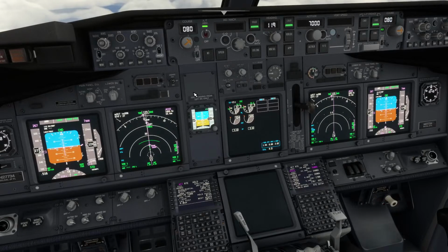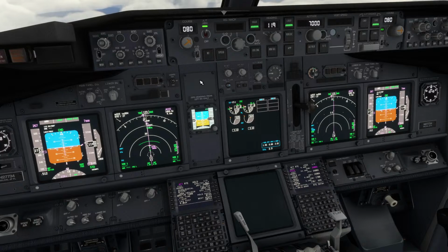If you lose that specific engine and you don't have system A, you have the option to retract the landing gear using the normal system. It's like the PTU on the 320, but this is a very specific situation. Yeah, you need to lose one engine and I think the system A, so it will give you the option to retract the gear in case you lose one engine, because maybe it's a bit tough for you to take off, especially if you lose the hydraulic system A and if you lose one engine.